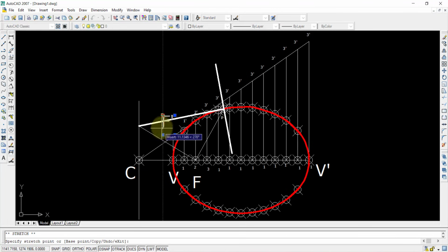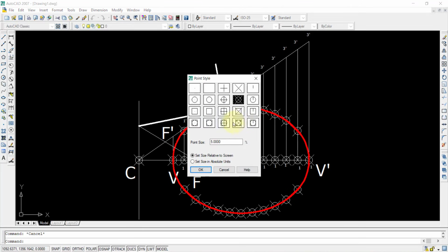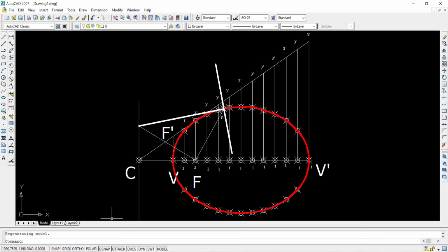Don't worry if you are getting confused, just go 10 seconds back and see how I have drawn the tangent and all. So it's very easy. We have selected the point first, then from there to F we have drawn 2 straight lines, and one straight line is tilted with 90 degrees, and that is extended up to the directrix. And from that point I have drawn 2 straight lines up to the point P which I have selected. Then one is tilted with 90 degrees, one is tangent and other is normal. So that is how you draw it. That is how you finish the ellipse construction by using general method.